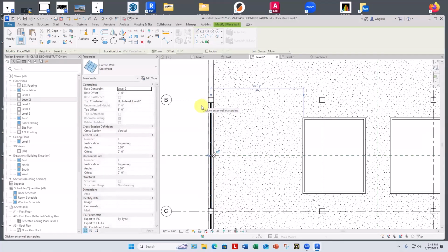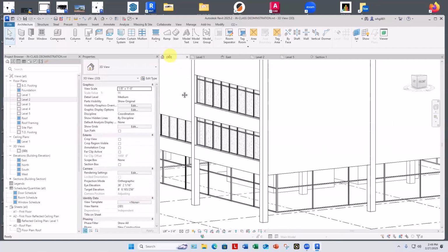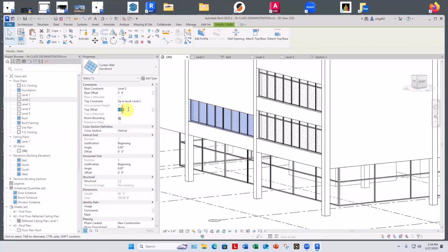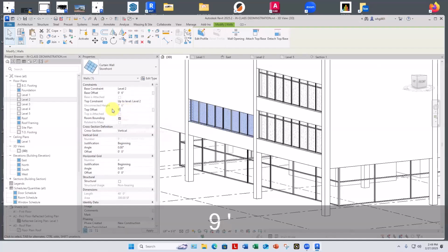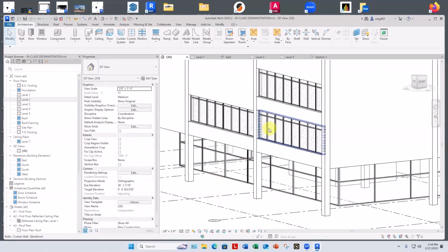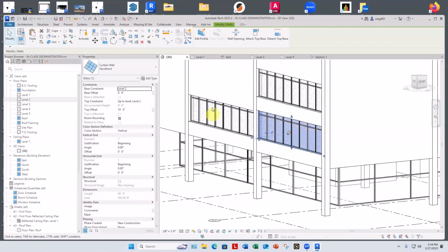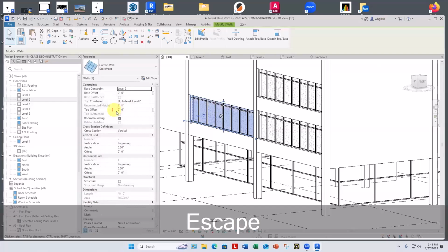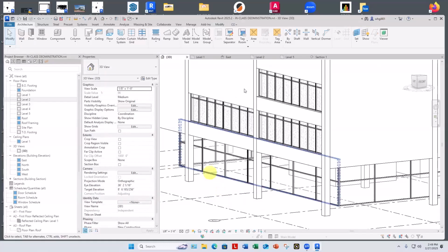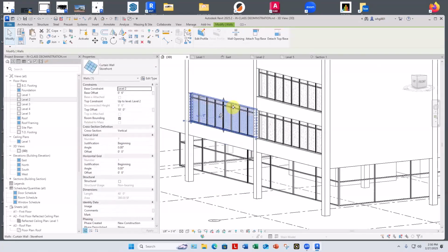I'm not going into the column or anything. So that's that. No, and I didn't set it high enough, but it's 9'6". Oh, top offset 10 feet, sorry. Okay, let's come take a look. So we're going 6 inches off the floor up to 10 feet high. And the total height of the thing is 9'6", but the top of it's at 10.